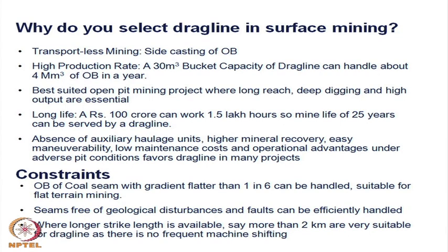The main benefits of using dragline are the absence of auxiliary haulage units, higher mineral recovery, easy maneuverability, low maintenance costs, and operational advantages for the other machines which will be working along with it. And to maintain a very good geometry of the pit is also possible with the help of your dragline. That is why we use this dragline.